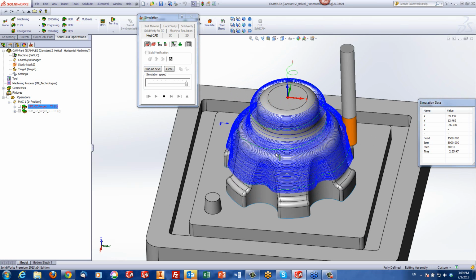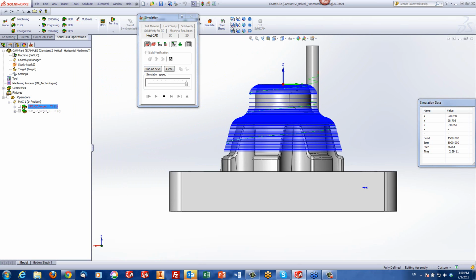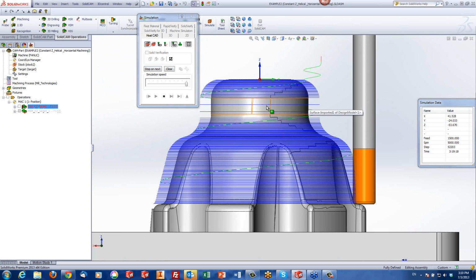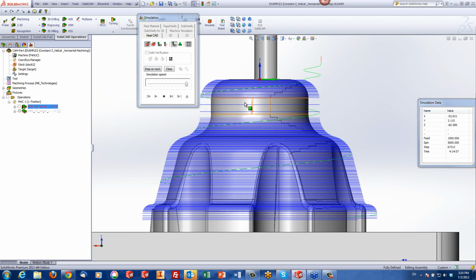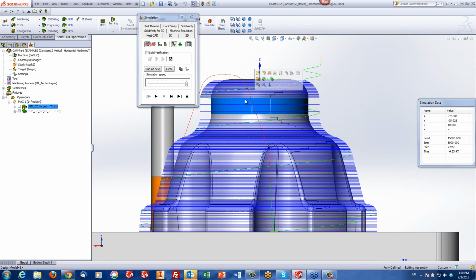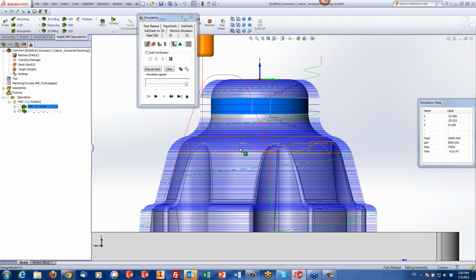We're going to go down all the way. Note when I look in the side view, you'll note that this area goes down every 3 millimeters. And that's because this surface around the part over here is a straight surface. So what's happening over here is that since it doesn't have anything underneath it, there's absolutely nothing to be taken off here. It'll jump down to its next 3 millimeter step. So this is actually the way you could control it to work quickly on these surfaces over here, but fine on these surfaces over here.